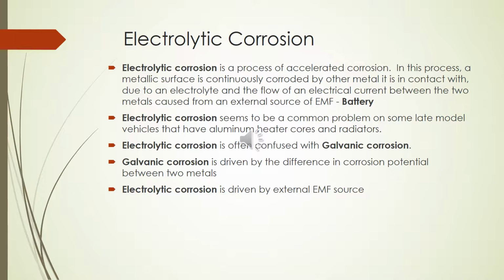Again, electrolytic corrosion seems to be a common problem on most modern vehicles that have aluminum heater cores and radiators. This is based on the experience that I have as someone who was working in automobiles for some years. I've seen so much corrosion occurring on a lot of heater cores. You replace them, and after a short period of time, you have to replace them again.